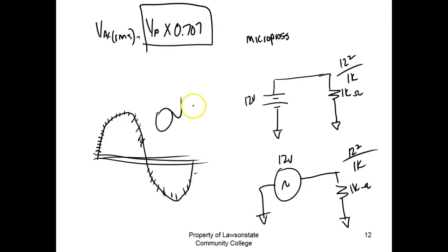That means they might come up and look like this, where this is okay, and then this right here might look like that. Now this meter, if it uses 0.707, it's not going to calculate it right because that is not a sine wave, right? It's still AC. So if you're dealing with devices like variable speed AC drives and stuff like that, and you want to see the average AC, then you're going to need a true RMS. If you're just dealing here, you don't need a true RMS meter, right? Does that make sense? Because you're going to pay about twice as much as you would for a regular meter. So this is where the 0.707 comes in. So this is what just about every meter you got in here uses.